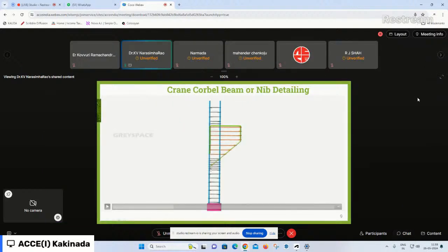This bent up bar, in this fashion, should meet the development length in compression for this bar. And for this location, from the outer face of the column to this point, the development length in tension should be met. The shear stirrups that we have calculated for the design shear should be accommodated within a depth of 2d by 3 only, not up to this point.